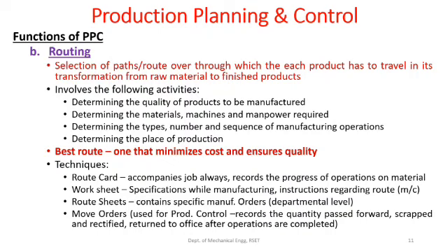Take the case of manufacturing a turned surface, say a bolt. It might require first plane turning a particular cylindrical rod, then carrying out a chamfering operation, and then a thread cutting operation. So there are a number of manufacturing operations that need to be carried out in manufacturing a particular bolt. These operations have to be carried out in a series or in a particular order. You cannot have first threading and then cylindrical turning.